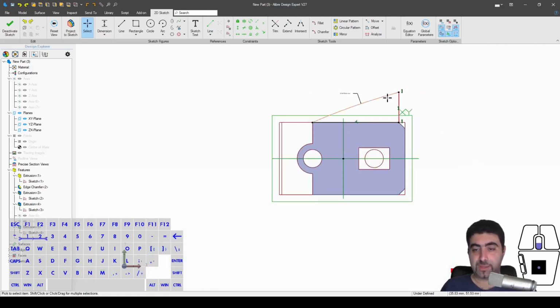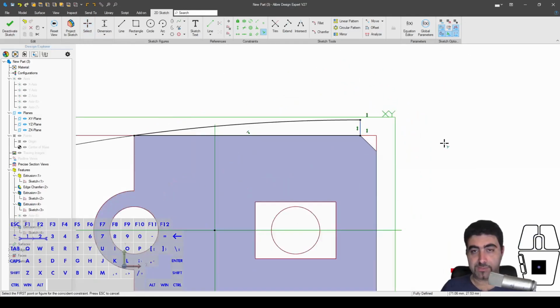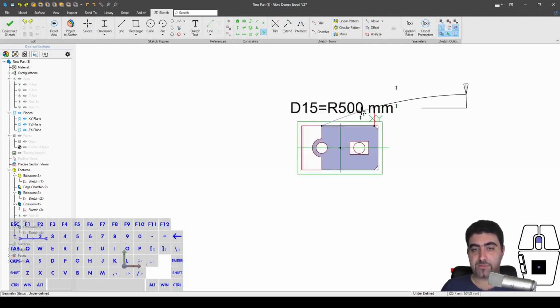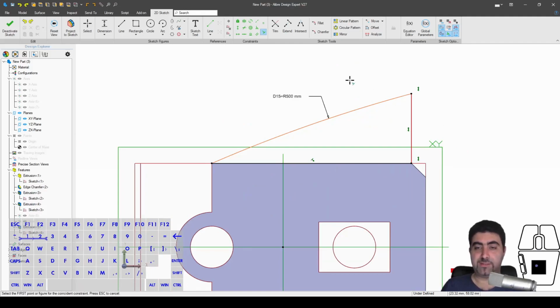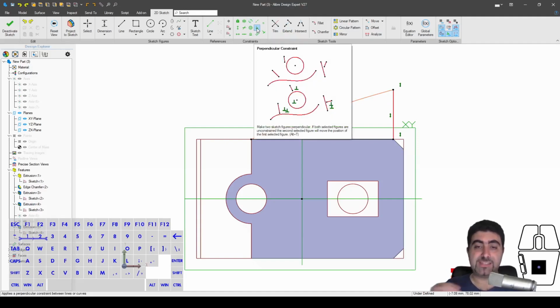Now, the way you would do that is you would just take the center and make it coincident to this line. But look, the center is down there. Imagine that this is in an assembly and there's like 100 things going. So how do you do that? Well, Alibre actually understands that as a perpendicular to a circle, right? A line can be perpendicular to a circle.